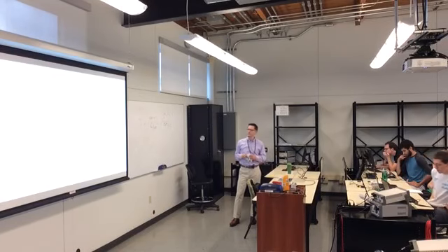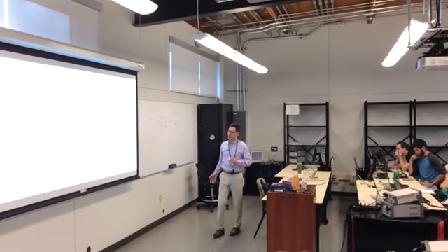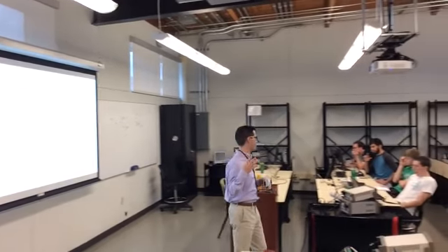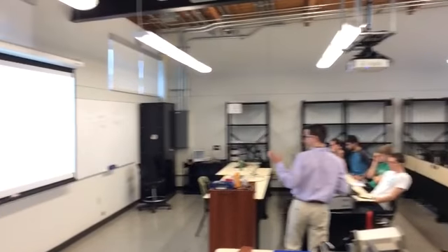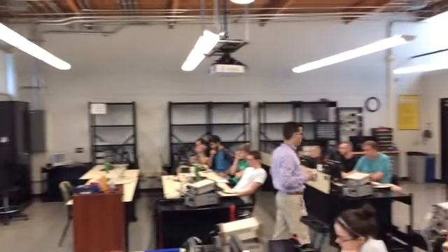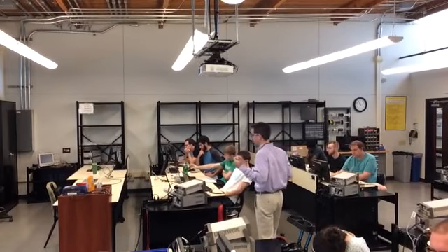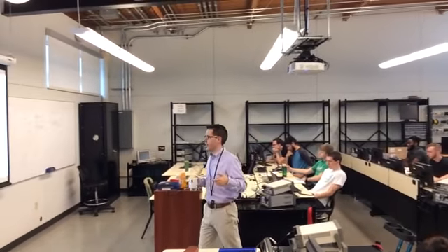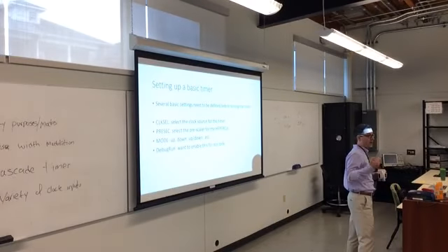And when you are going to set up your timer, there are four things that you've got to do before you actually configure it. You've got to pick what clock it's coming from. Is it the peripheral bus? Is it another timer? Is it an external clock? You've got to select how much that clock is then scaled by. It's going to be some power of 2, so 2 to about 1024.